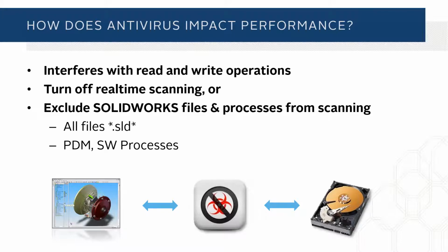And what I would submit to you is the most low-risk but performance-enhancing way to do this is to exclude any file that has a .sld in it. So *.sld* is the file mask, which means SLDPRT, SLDASM, SLDDRW, but also library files, SLDLFPs, templates, anything that is a SolidWorks file.